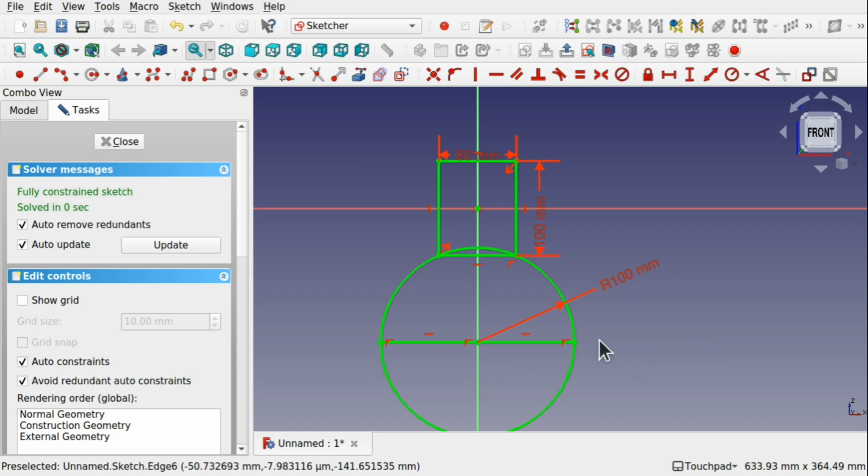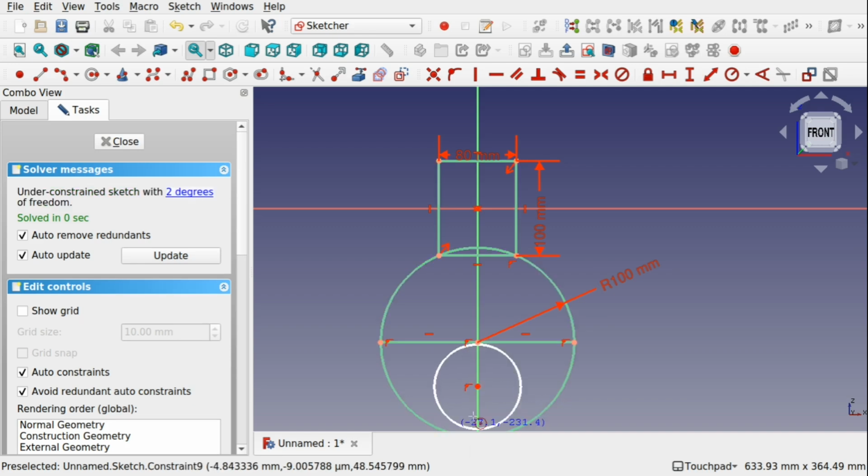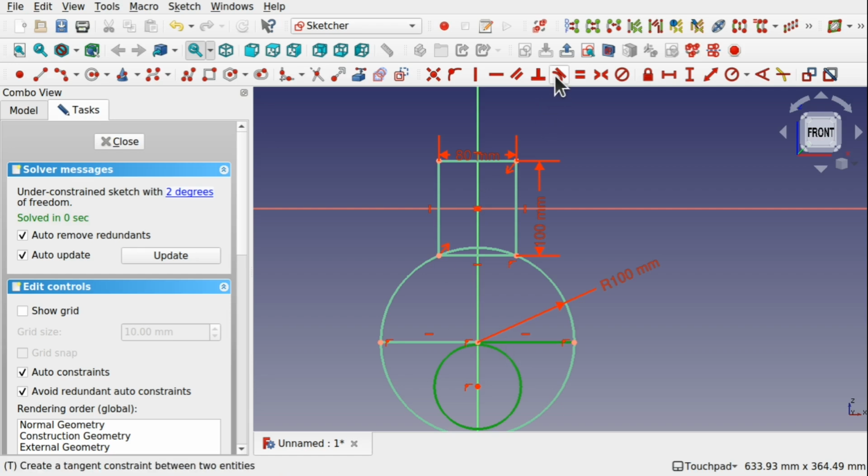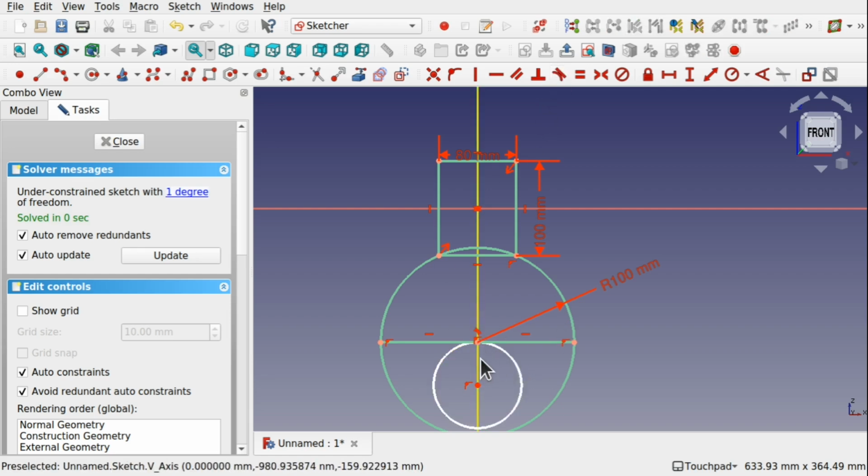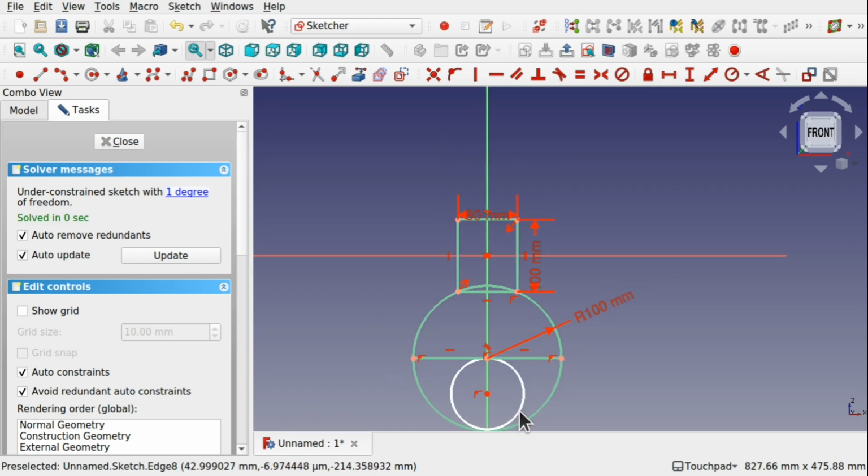The reason being is I'm going to create a circle down here to get an idea of how this crankshaft should look. So we're going to create that circle now. Place a circle in here. And this is where this piston will be connected to a control arm, and it will be connected to this circle here somehow. So we've got the circle there, and what I'm going to do is take this circle and this line and create a tangency constraint between there, so it sits on that line. Then I can adjust this to how I see fit.